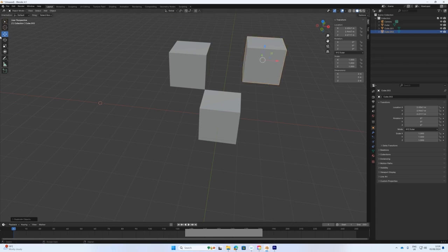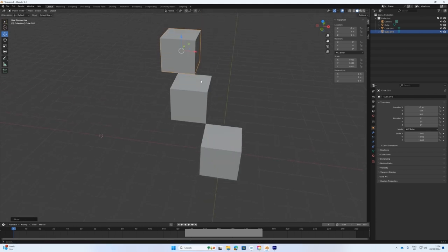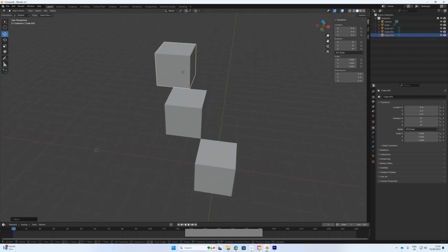And even if I don't have anything, I press G. Keep the left mouse button down, press B. Still, the mouse button is down. And I said, okay, this center of this edge now, this is what I want to snap. Where do you want to snap? I want to snap right there. Okay, and then I can do the same thing now.